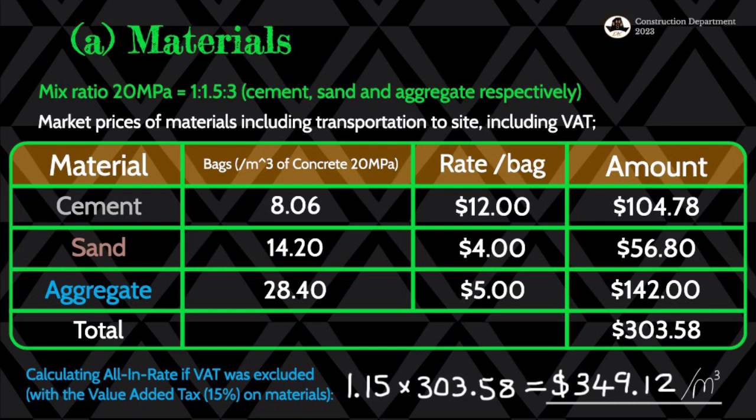That's the cost for that 1 cubic meter, which means we're going to use this price to multiply with the amount of concrete we are going to be using in the total concrete for the entire project, either for slab, for foundation, for the story floors and the like, or for even the walls. If we're going to have some concrete blocks for walls that maybe are not precast, that are in situ, we're going to even have lintels. That's maybe the rate that we can use. Or if the lintels need a different mixture, then we'll start again with the target strength that is needed for each and every part. So this is specifically for 20 mega pascals.